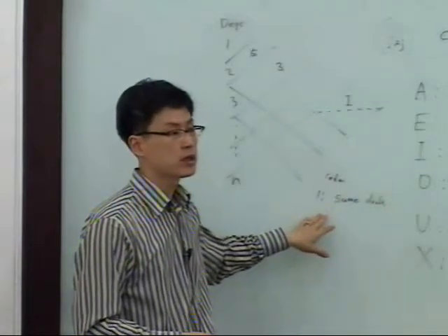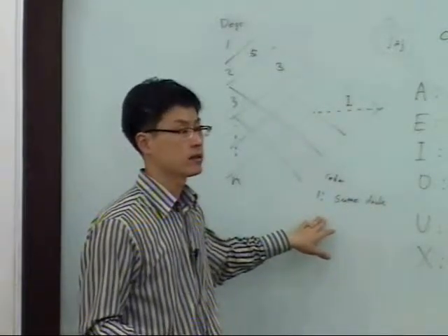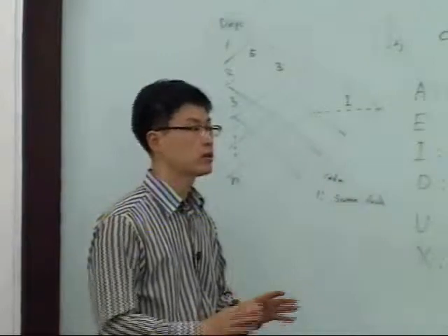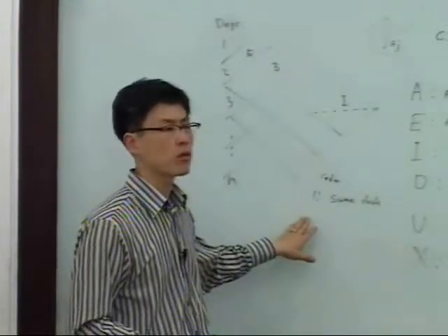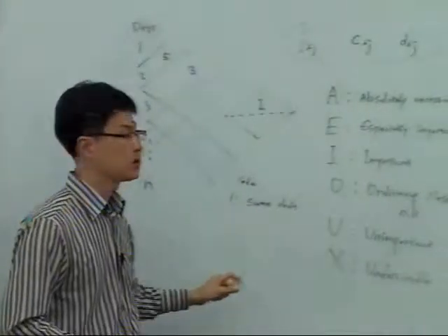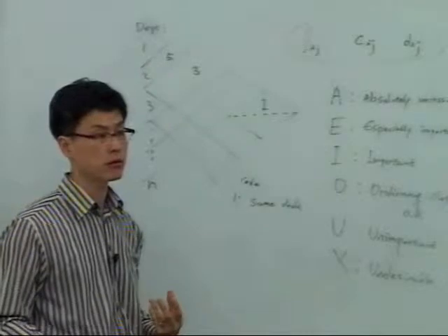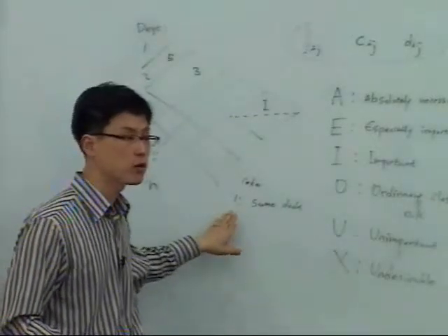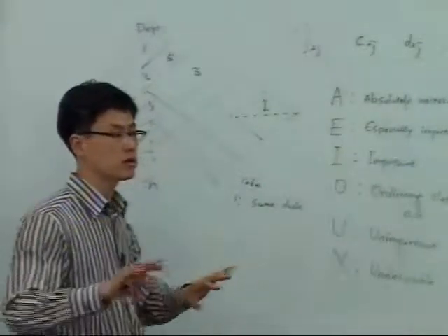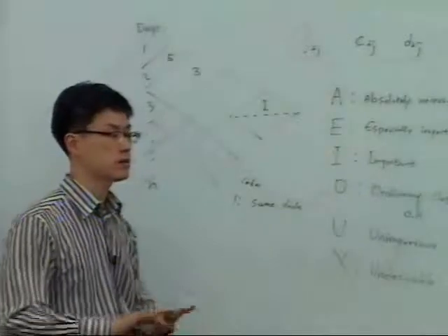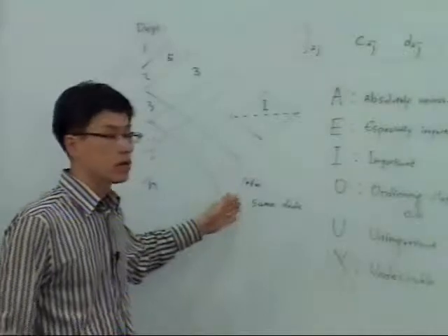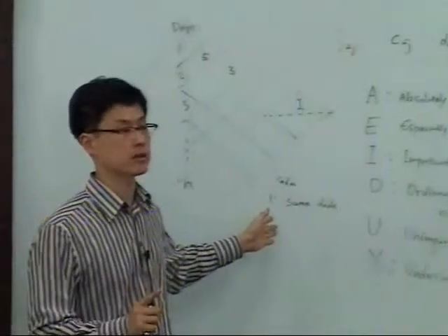The type could be anything. For example, as I mentioned, a floor type, a lane, or something like that. Or the reason why we require the importance of affinity between 1 and n. Is it because of material flow? So we can specify number 1 is material flow, number 2 is information flow, number 3 is toxic material, number 4 is the sanitary problem, and the like. Okay? The important thing is to be consistent.